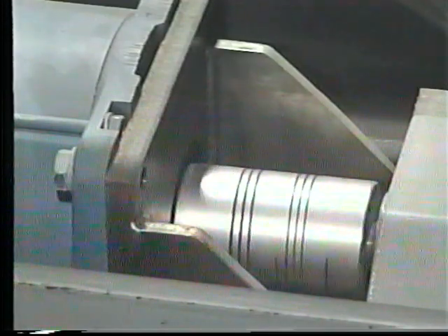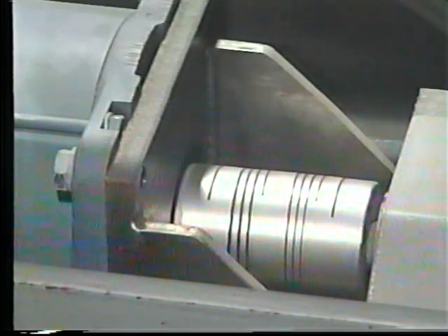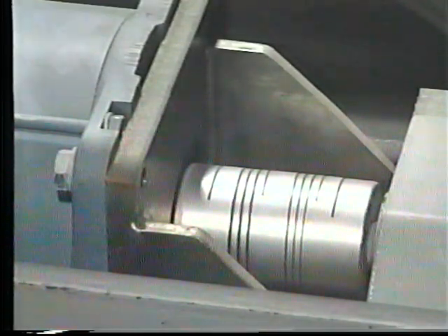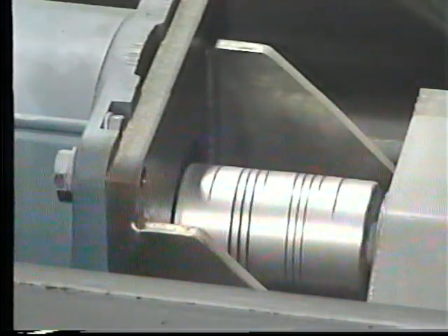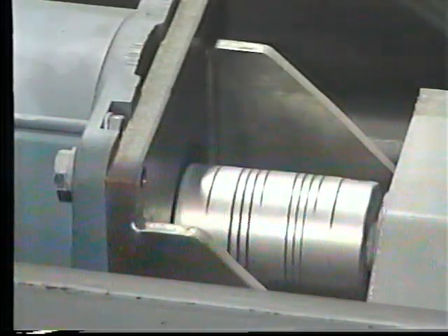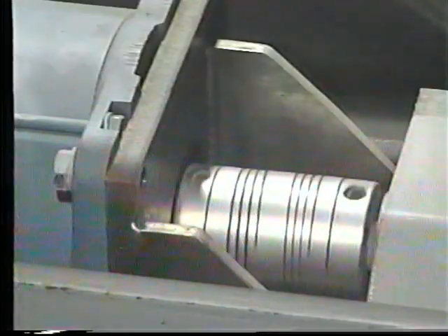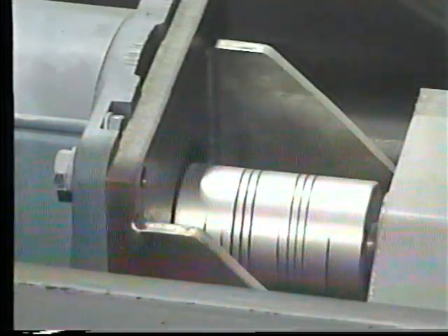Sometimes flexible couplings have a significant amount of backlash. This means that there is lost motion or slack in the unit when the direction of rotation is reversed. Some flexible couplings are designed to reduce the backlash. Another factor that may affect coupling selection is end movement or end float in one or both of the shafts. This backward and forward movement along the length of the shaft may require a special type of coupling.